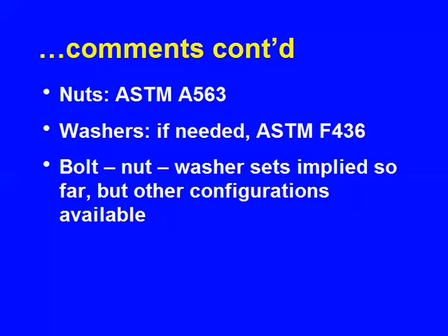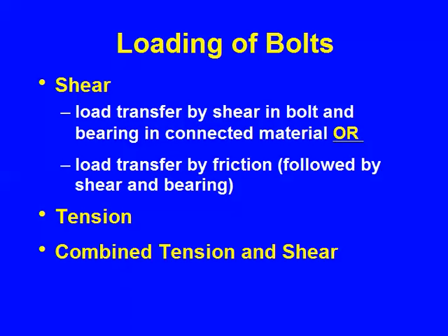If we need washers, we don't always, and there's a specification for them. There's sort of an implication to this point that we're talking about bolt, nut, and washer sets, and often we are, but that's not always the situation, and other configurations are available. With that introduction about what we're using, the fastener itself, let me talk for a few minutes about the loading of the bolts.